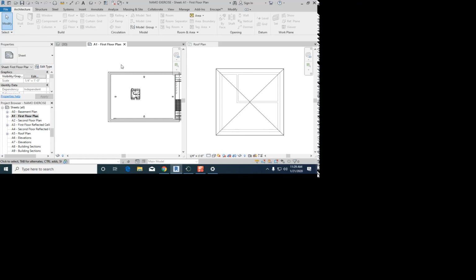Oh, okay, I knew what this is. It's QD. Why don't we use or rely on quick dimensions? There's like 10 things that came up. They're not reliable, and they're not to the face of the wall. Yep, they go to the center. So we can fix it by clicking on them, but really it's probably faster just to draw your own and move on with it.